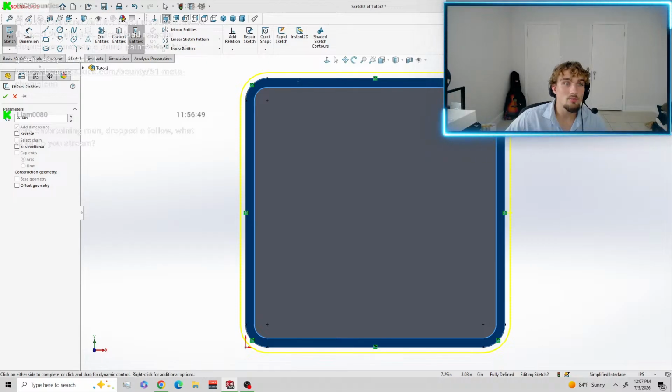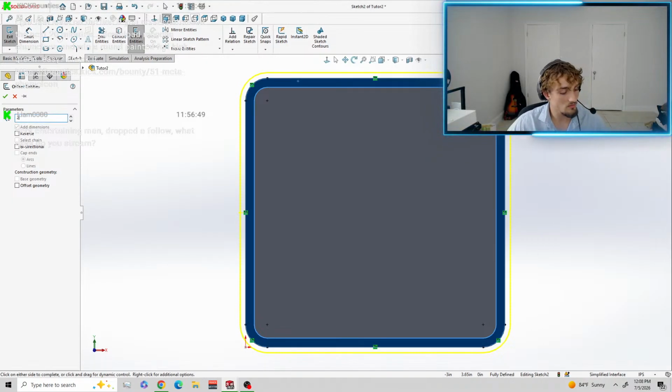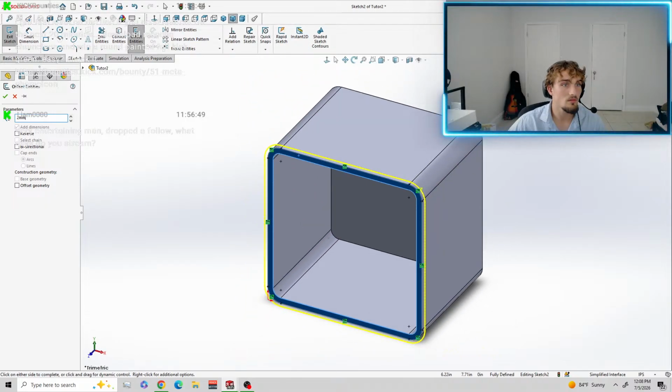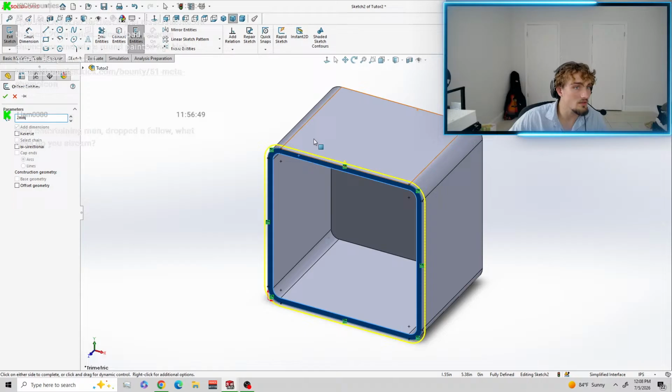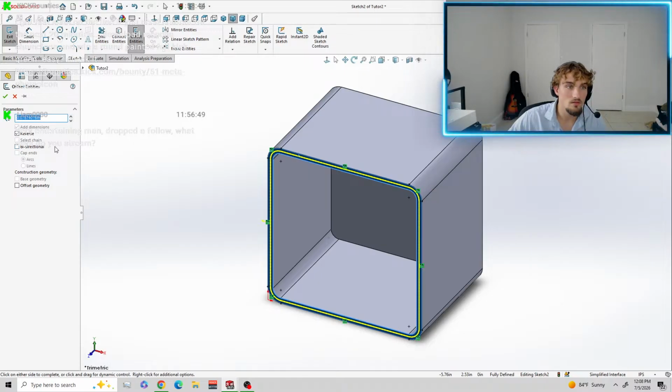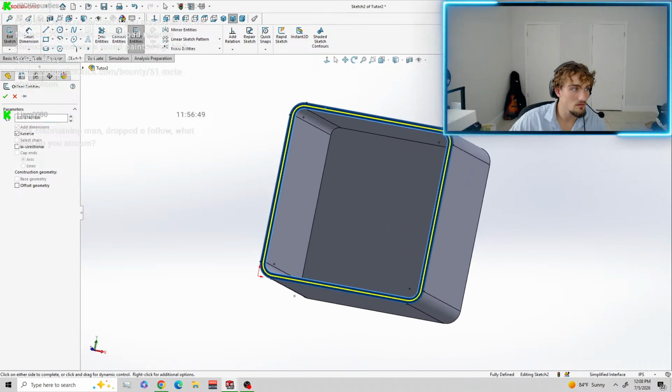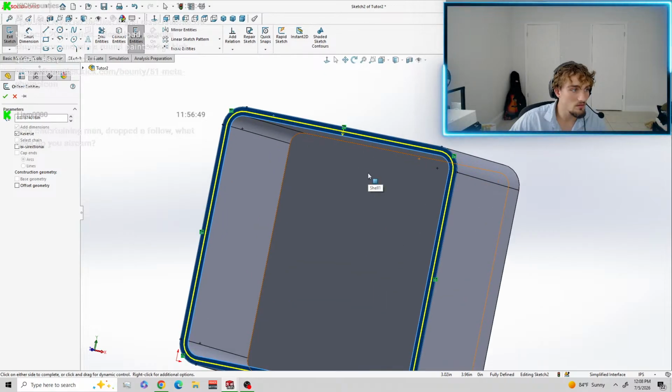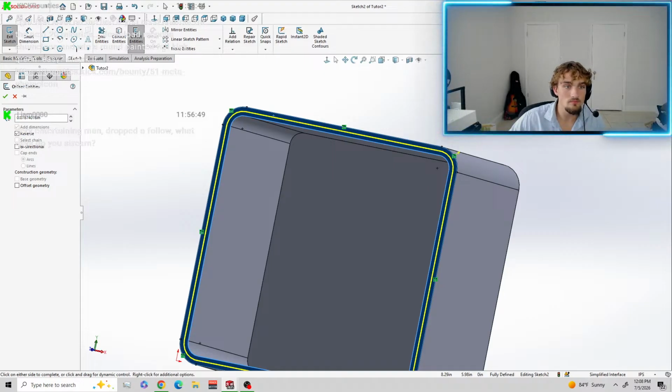In the offset entities property manager under parameters, set offset distance to 2. The preview shows the offset extending outward. Select reverse to change the offset direction. Reverse. Okay, click check. Sketch offset from the outside. This relation is maintained if the original edges change. Okay. Check.